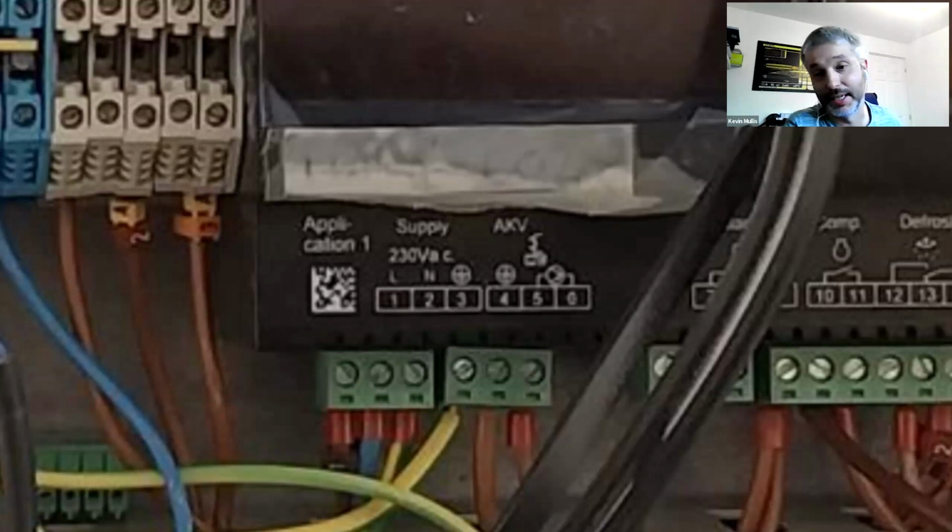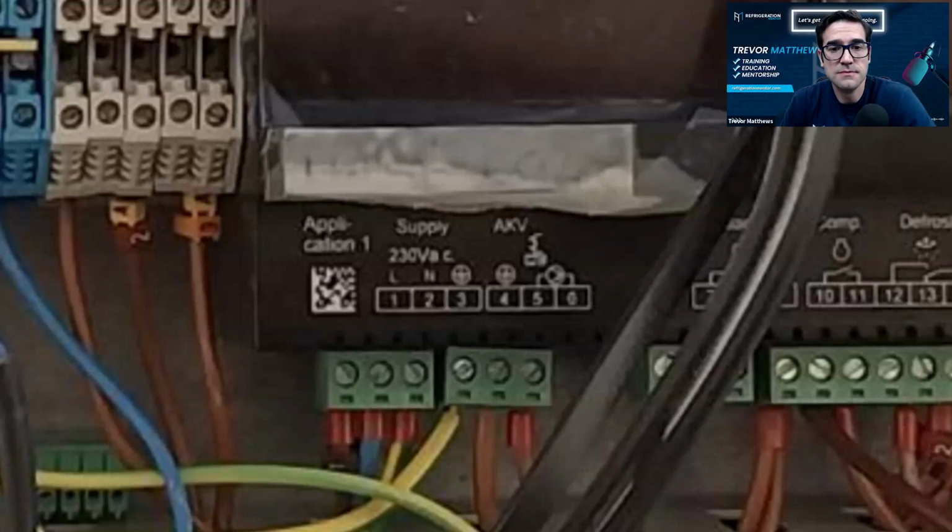What you're going to see is probably 3-4 seconds at the most on and then off, and on and then off. The standard timescale that Danfoss works on is 6 seconds. So you will get a percentage of 6 seconds on depending on how much valve drive it's asking for. So yeah, just check you've got a voltage out to your coil.